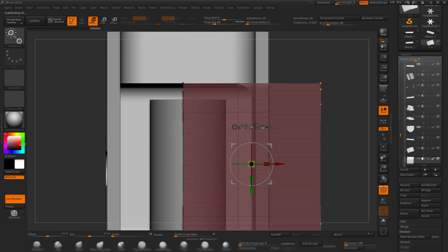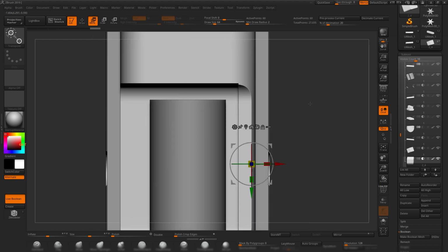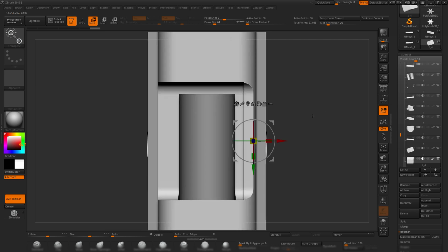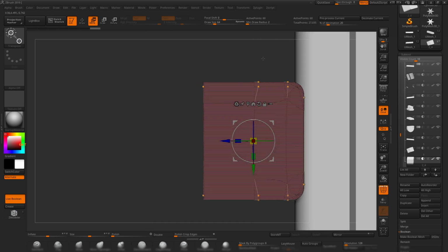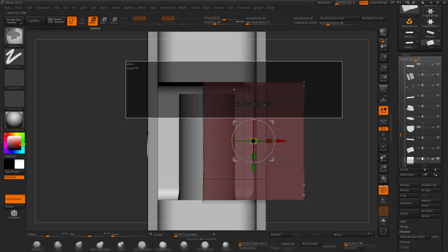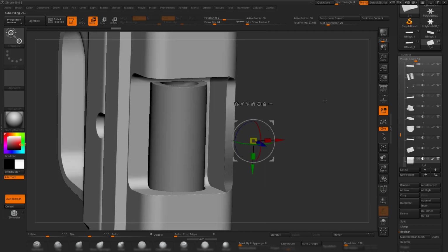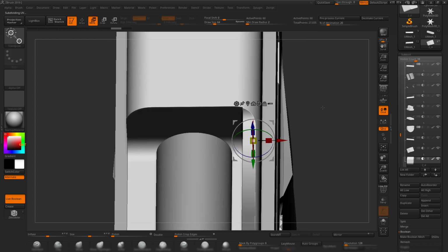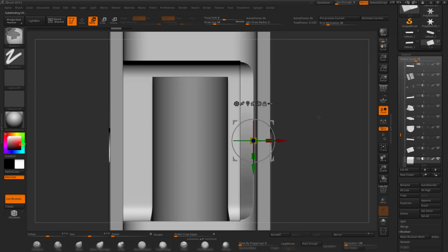And you can see, because I'm not going the whole bevel, the bevel itself is not making it the whole way through, and you can see that it's not touching the tip. So just select this guy and move it until it fits there. Oh yeah, there's a problem there. Okay, no problem.